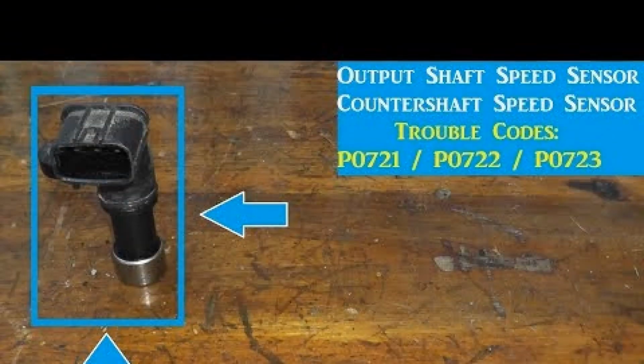Check the wiring harness connector for PCM/ECM power, using the factory wiring diagram as a reference. Place a multimeter on the volt scale with the positive lead on the PCM/ECM power cable, and place the negative lead on the ground. Depending on the vehicle model, the voltage reading should be 12 volts or a reference voltage of 5 volts. If the voltage is not within specification, an earth fault may be suspected. Also don't rule out a faulty PCM/ECM or a wiring problem between the gearbox and the PCM/ECM.